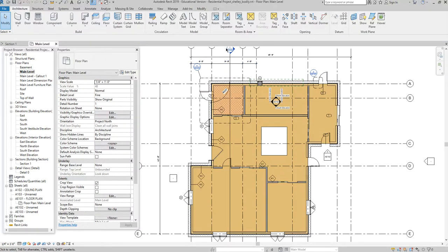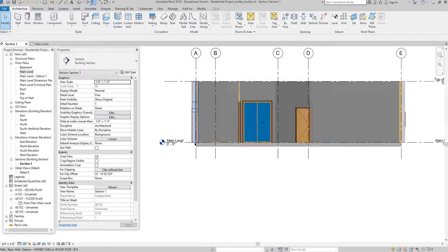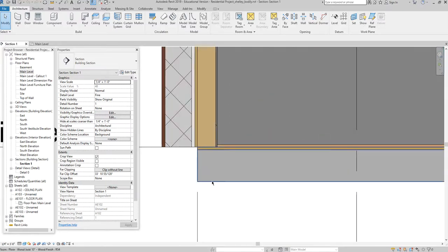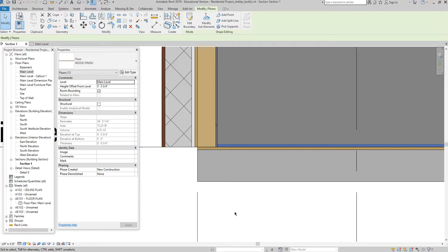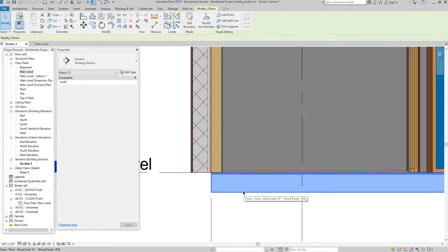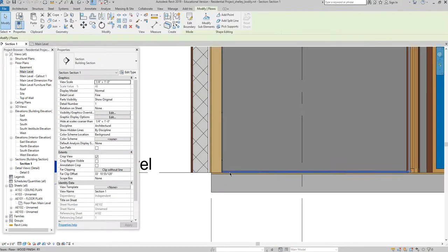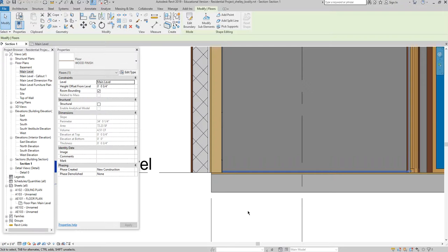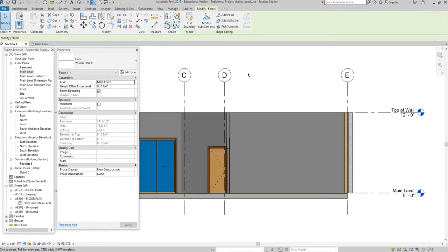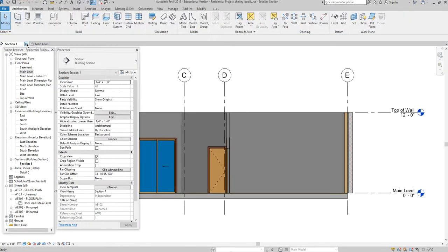So really, when you are drawing your floors, you're working professionally, you're going to draw your structural floor, and then you are going to draw your finished floor on top of that, okay? And we do that so that you don't have a bunch of little pieces of floor all over the place for the structural floor. You have one cohesive slab, and that seems to function very well. And then you can change the finish using those individual finished pieces, okay? So that seems to work pretty well.